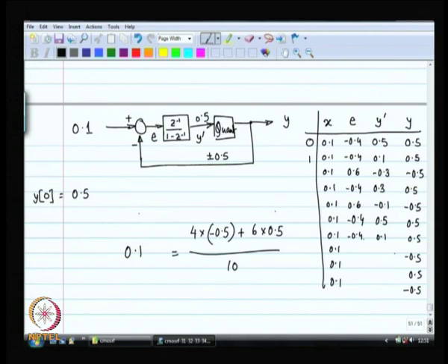The unfortunate part over here is that the cycle repeats itself. So, first of all, this is the basic sigma delta modulator. This is called a first order sigma delta modulator. The cycle is repeating itself, which means that you are still stuck with periodicity, and as long as you are stuck with periodicity, you are going to see spurious tones at your output. So, this is still not exactly what you want.